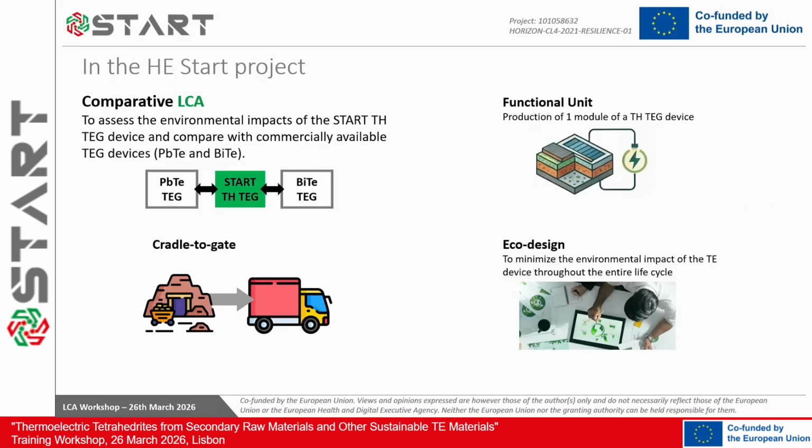So in the context of the START project, the focus was mainly to do a comparative LCA, to characterize and assess the environmental impacts of the thermoelectric devices being developed within the project, and also, because we are introducing a new material, to compare that with the predominant and more commercially available alternatives, which in this case we chose to be lead telluride and bismuth telluride.